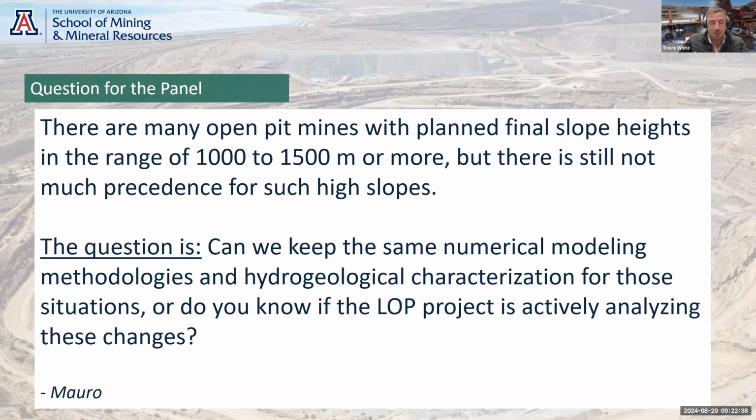So there's a good additional benefit that if you develop a drainage gallery at the right point in time, that can act as early access or permanent access for the underground mine in future, as well as, well, not cheaper to build a gallery, but you'd have access for resource characterization. So you can do drilling from underground to better characterize the resource.